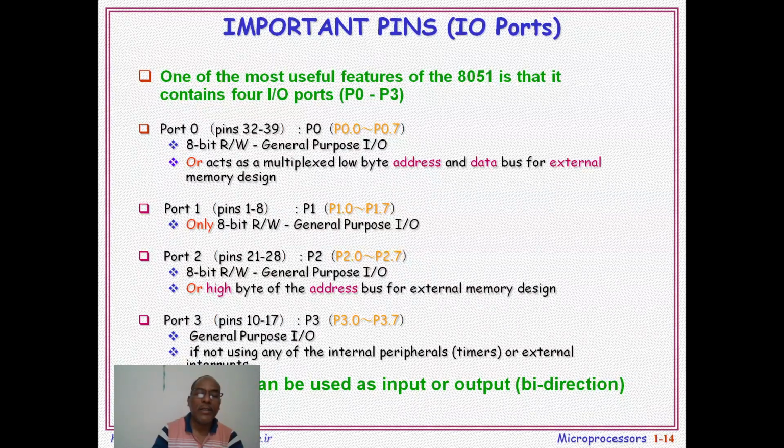Then port 3, that means pin numbers 10 to 17, is for general purpose IO. If not using any of the internal peripherals, that means timers or external interrupts, each port can be used as input or output, bidirectional.